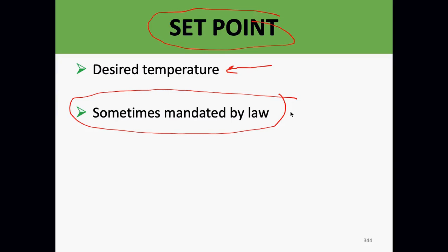Normally, it's 70 degrees on the heating side and 75 degrees on the cooling side. That's what our normal mandated set points are.